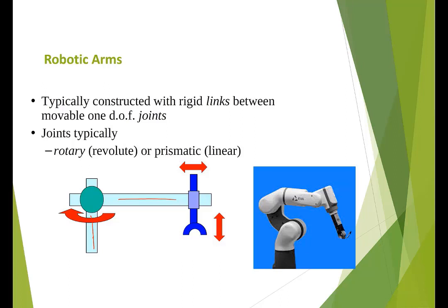For instance, this very simple robot that we see here, a schematic of the robot, is used to pick an object and move it. It has one rotary joint here actuated with a motor and two linear joints that we sometimes call prismatic joints, and the rotary joints are sometimes called revolute joints. Revolute joints move a joint by an angle and linear joints move it by a specific distance. So a robot can have any of these joints, prismatic, linear, or rotary and revolute.